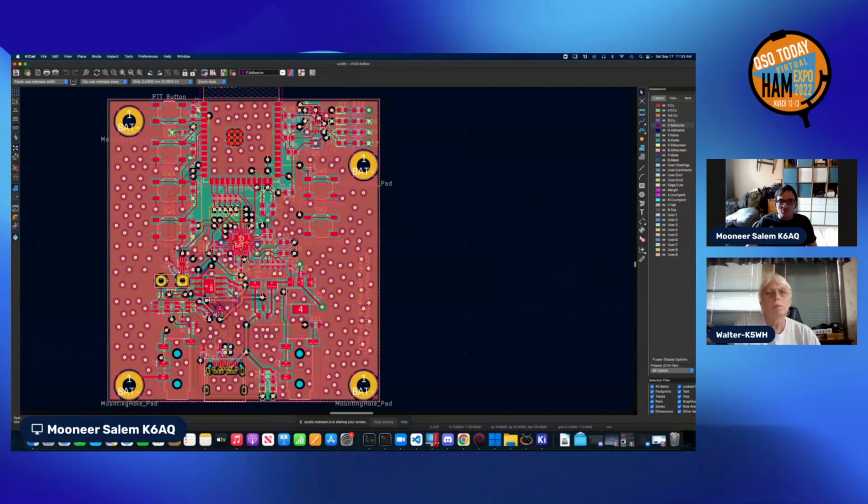This component that's labeled 33 is the TLV320. And this portion over here is basically the battery charging circuitry and the LDO to convert the 4.2 volts for the battery, or 5 volts for USB, down to 3.3. And then there are two 3.5 millimeter jacks down here. One of them, I believe it's this one, is for the headset, and the headset is basically wired for Android.